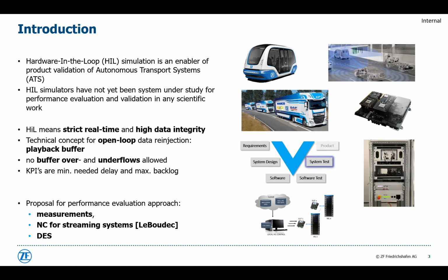The technical concept for open loop data re-injection, which is one mode of hardware-in-the-loop simulation beside the closed loop simulation, is to use a playback buffer. No buffer overflows or underflows are allowed. That's why the KPIs are the minimum needed delay and the maximum backlog in the system.